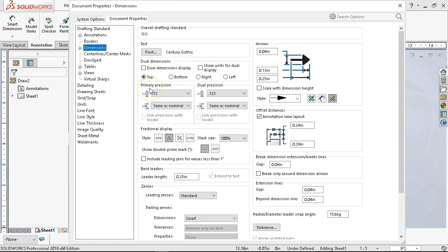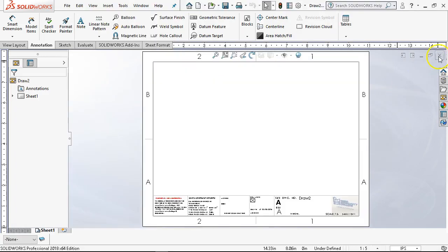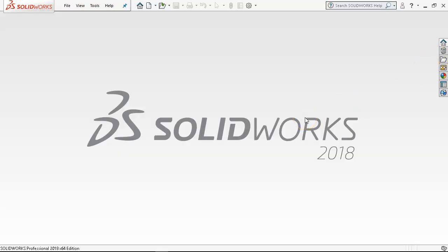If I wanted to always dual dimension, I would have to set that, and I believe save it to either the sheet format or the drawing template. That's one that I'm still not real clear on where exactly those get retained. So one of the reasons that I go File, Save Sheet Format is it updates. And then when you go into Save As Drawing Template, and it may not be necessary because you can reload, rebuild. It kind of saves that separate step of updating.